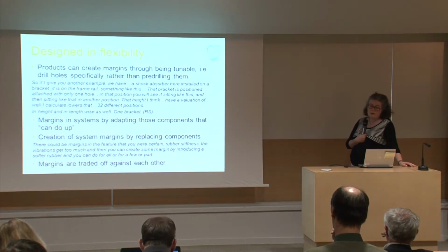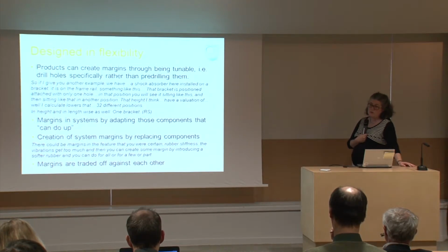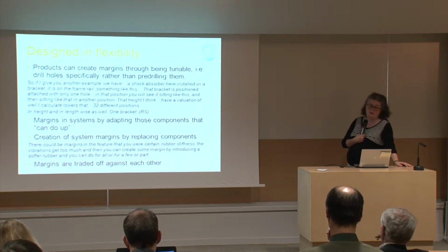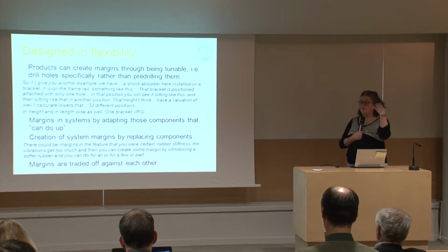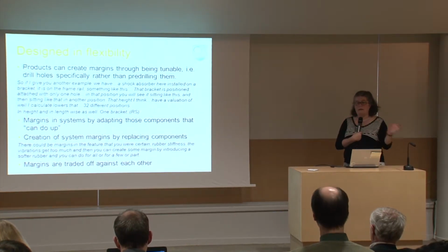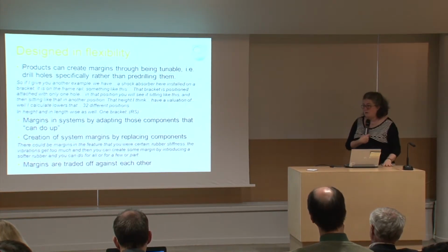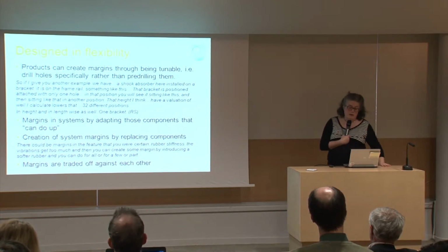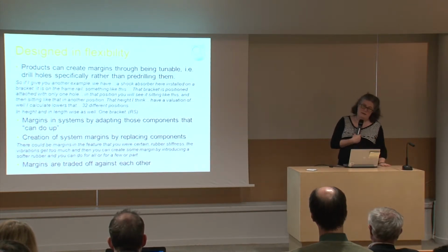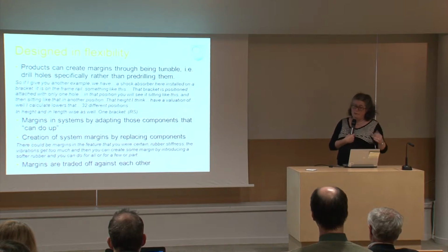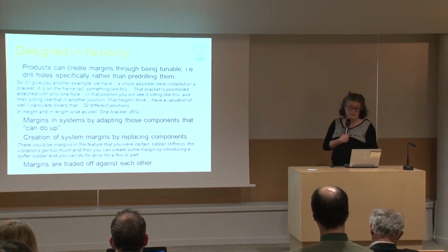But sometimes you can also design margins into a solution itself just by being quite clever. And I think here they have the example of, instead of having a hole to put a screw in, you draw a slit, and then you can put it in different positions, and the same thing can be used. So in some ways, this isn't strictly a margin, but it does give them flexibility.